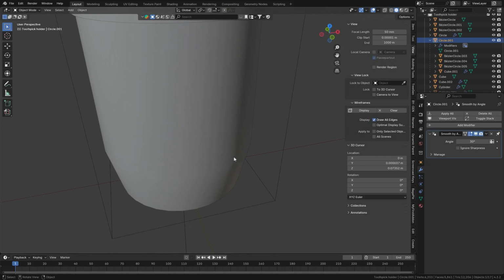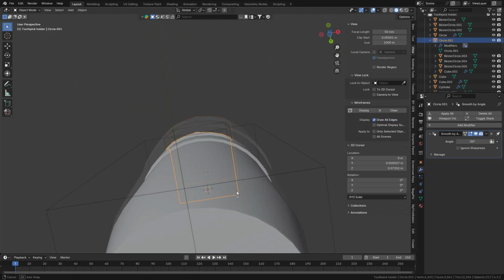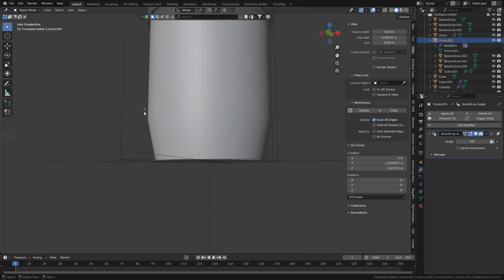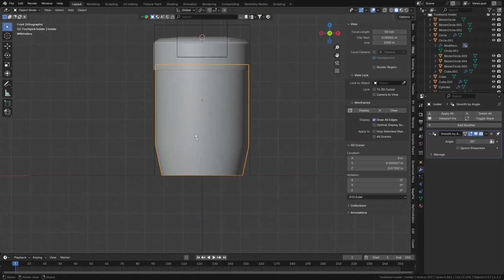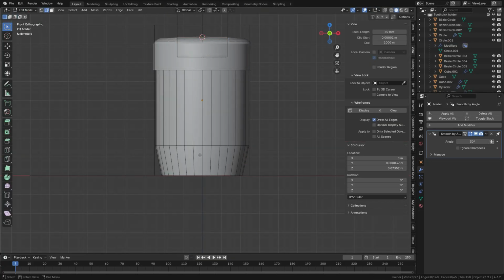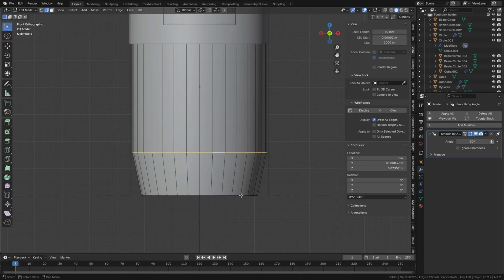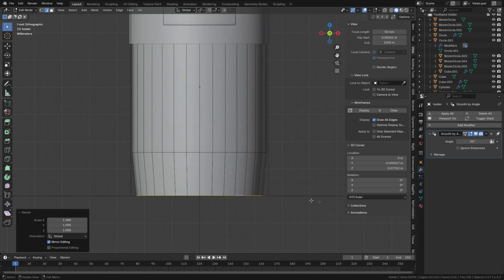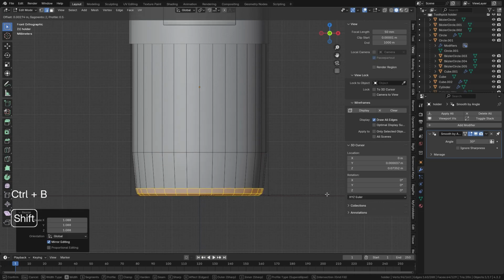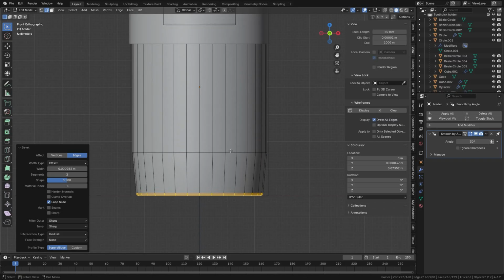So what you just want to work on here is the bevel for the body. Then I think we are done for this part. Go to edit mode, select this, rather all select this, scale this up just a bit. Okay, fine. Press Ctrl B and just a little down here, should be about okay.